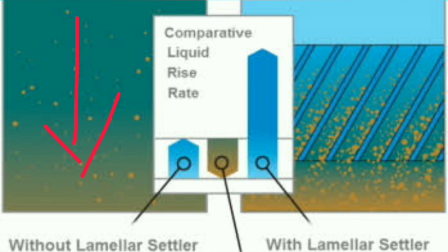Because of that, the particles that settle at this point cannot stay for a longer time. They have to slide down to the bottom. With this effect, more particles will be settling to the bottom. This is the idea behind the tube settlers. And these can capture the settleable fine floc that escapes the clarification zone beneath the tube settlers, and it also allows the large floc to travel to the tank bottom in a more settleable form.